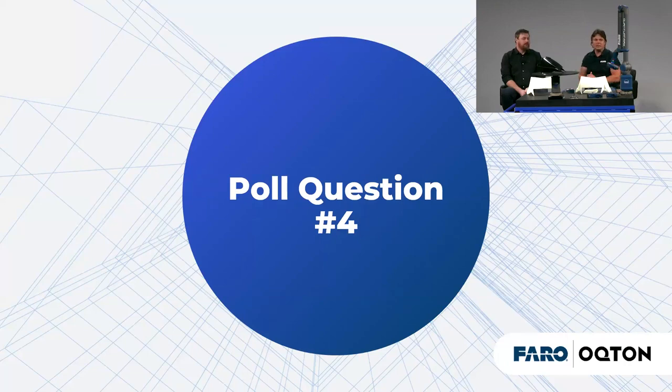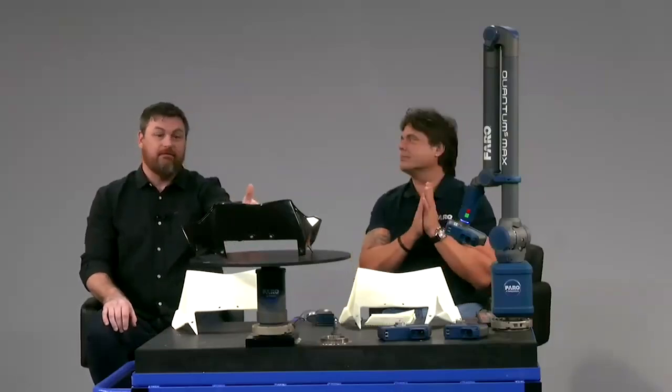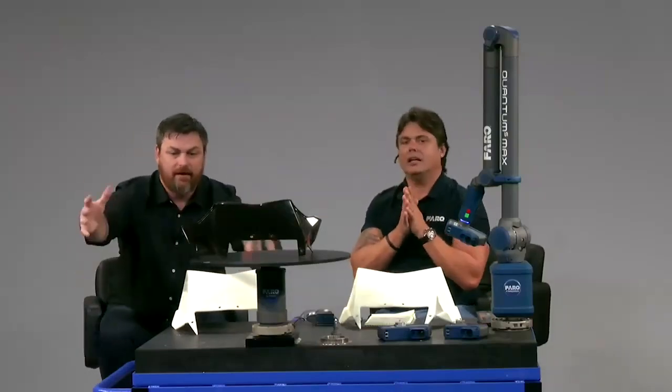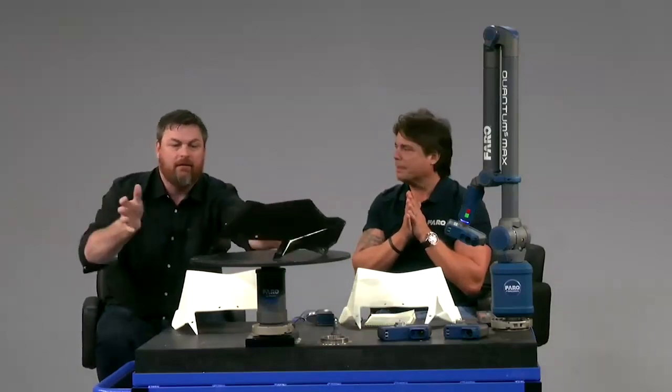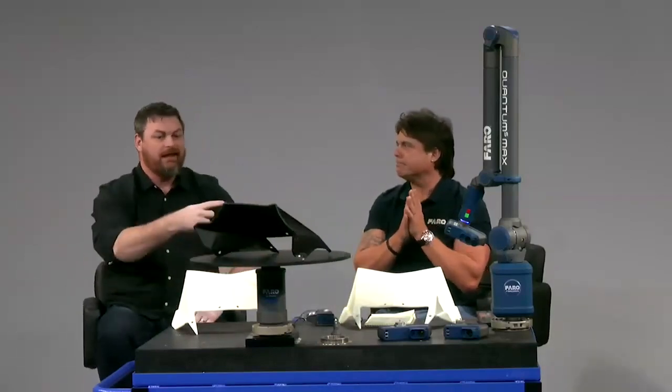And again, I like to say that because sometimes you want to move not the arm because of size, but you want to move your part because of reach. Maybe you have something to measure on the underside. The other thing I point out is the 8th axis can extend the volume, because if the part is sticking out this way and I rotate it around, I can bring it in the volume of the arm. Yep. And it almost extends. Absolutely. I mean, it does extend the volume.